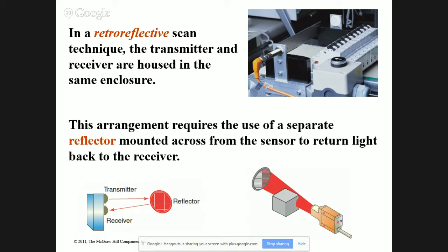Now, why would we want to have a dark operated photo eye? In this instance with a reflector. Well, you did that at counter, too. Yeah, but here's the deal. If this was on a packaging line running a lot of boxes and it was dark operated, then when a box fell off and knocked this reflector off, the system would know that either there's a package in the way or the reflector got broken or knocked off.